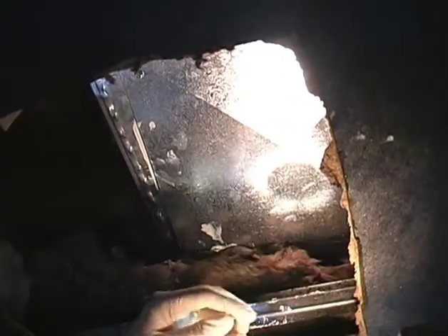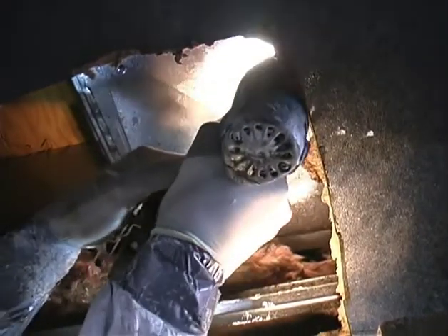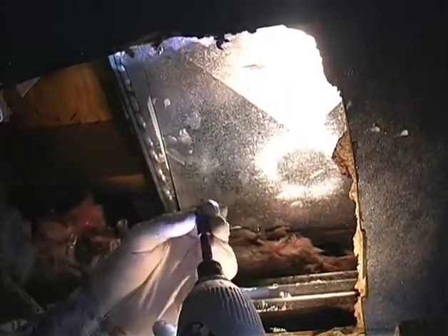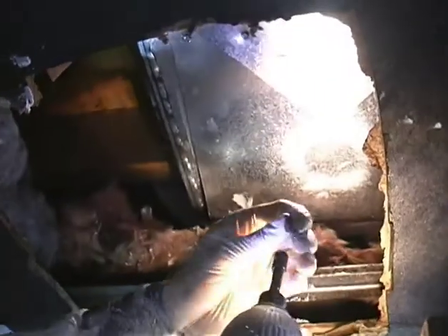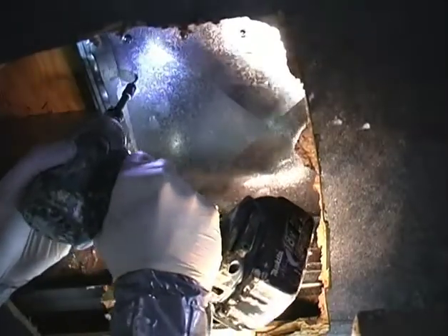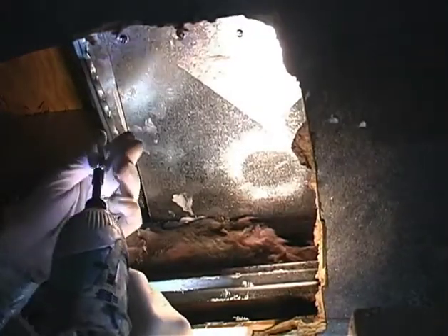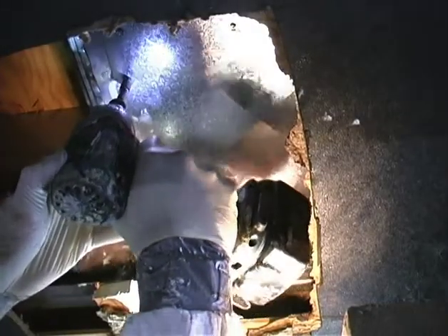We usually put a screw in about one every 1 to 2 inches and make sure that that mastic does a little squeeze out so that we're assured that the patch is doing the job for us. If he's concerned that his patch isn't taking so well, or it's not conforming well to the bottom of the trunk line, he will go ahead and seal the edges of that patch with mastic and embed some fiberglass tape in that edge of that patch if he thinks he needs to.